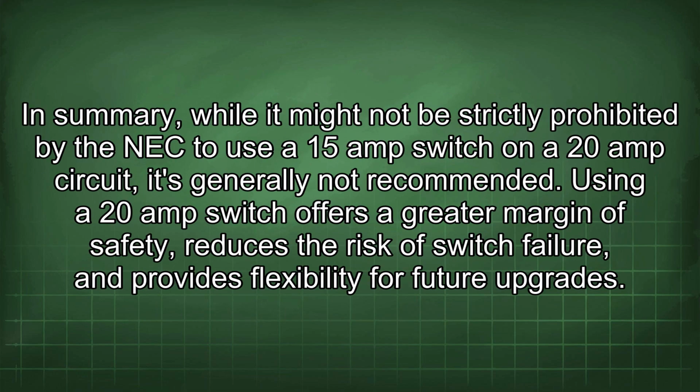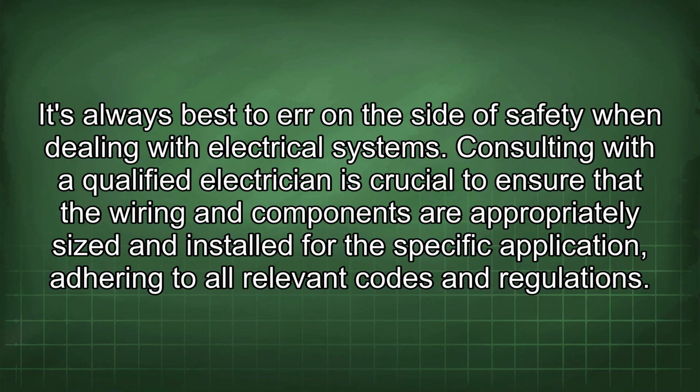In summary, while it might not be strictly prohibited by the NEC to use a 15 amp switch on a 20 amp circuit, it's generally not recommended. Using a 20 amp switch offers a greater margin of safety, reduces the risk of switch failure, and provides flexibility for future upgrades. It's always best to err on the side of safety when dealing with electrical systems.